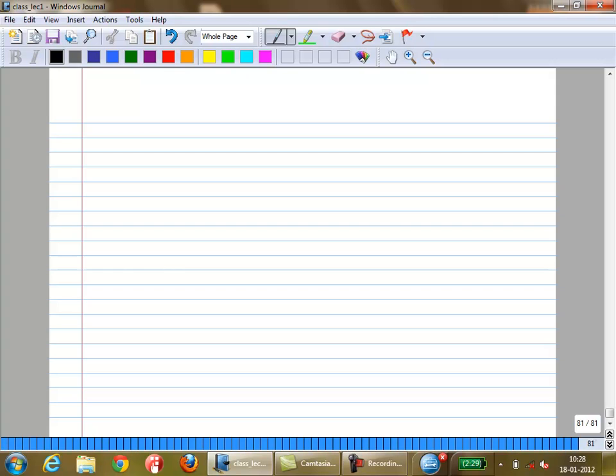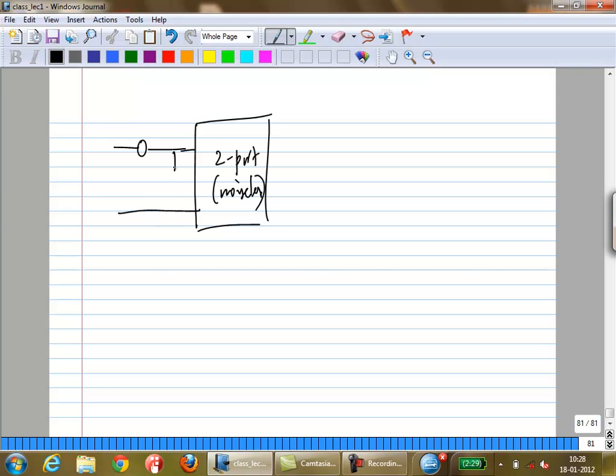So in terms of circuits, we tend to represent it as, let us say this is some two-port network. You're going to convert it into a noiseless two-port with an equivalent noise voltage and an equivalent noise current at the input, a shunt noise current and a series noise voltage.